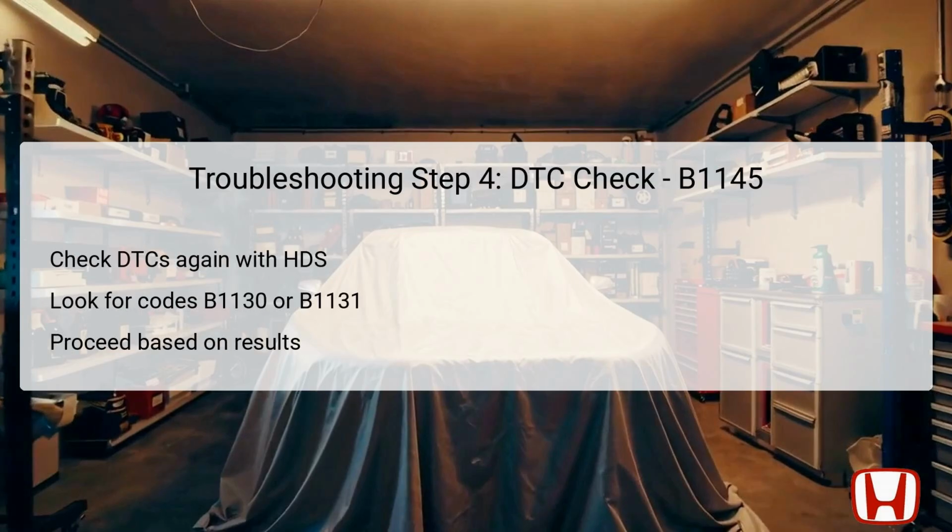After manually testing the passenger window, the fourth step involves checking for DTCs again, using the Honda Diagnostic System, HDS. This step is important to determine whether any new trouble codes, such as B1130 or B1131, appear. If either of these codes is present, it indicates that the issue may not solely be related to the B1145 DTC and requires further investigation into the new codes.